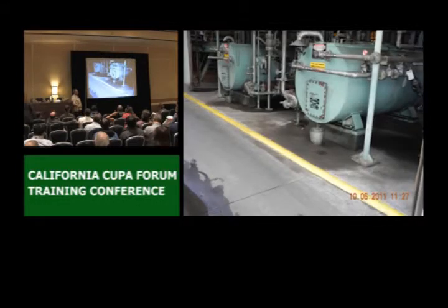At some facility, like their warehouse facility across the bay, right? Big, huge warehouse. They're going to store like 400 drums, right? Certified plant, all inside. How much containment do they need for the 400 drums? Fire code aside, it's not a fire code issue because they're class 3Bs, right? Individual pallets or really good peel and stick or molded, installed like 1-inch or 2-inch berms around the roll-up doors and the exit doors. That was it. It'll hold it. OSHA stripe, just in case. Anyway, just an example. That goes to the separator.